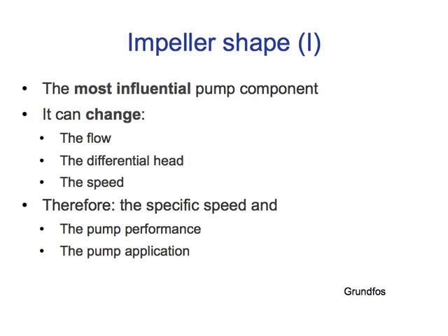The impeller is the pump component that has the most influence on the pump performance. Actually, you can create a brand new pump by just modifying the impeller. It can change the flow, the differential head, the speed, therefore the specific speed, the pump performance and the pump application.